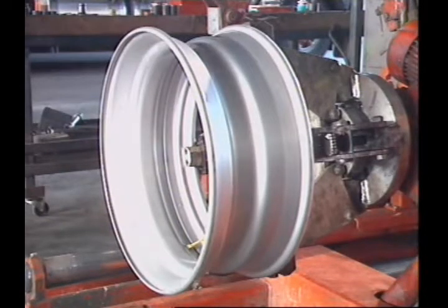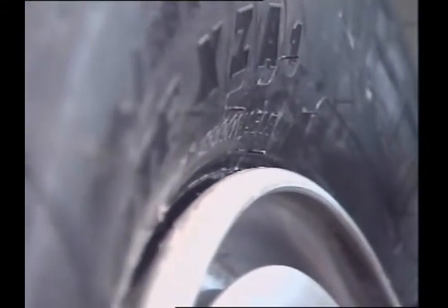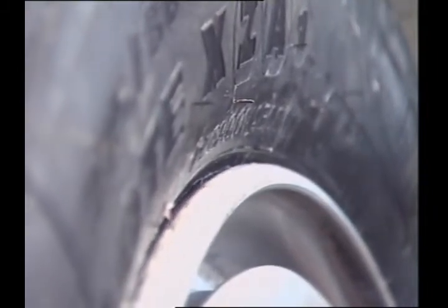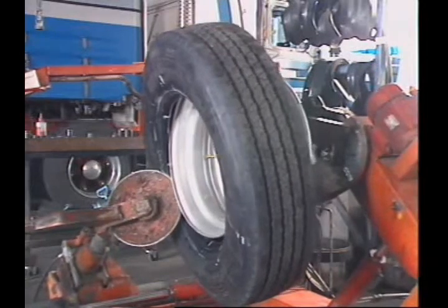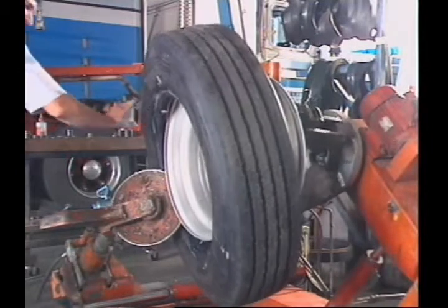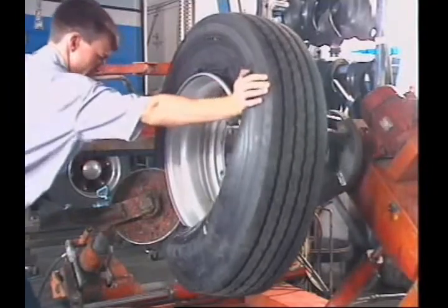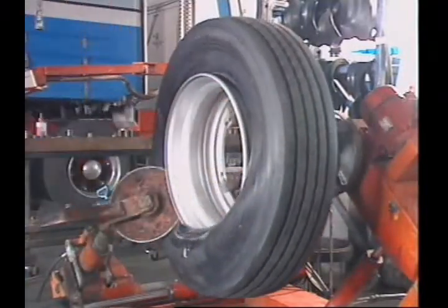Well-based rims can also be used on heavy commercial vehicles for tubeless tires. The rims are referred to as 15-degree drop center rims because the bead seats are inclined at 15 degrees towards the flange. The taper gives a good grip and an airtight seal between the tire beads and the rim. The low flanges and drop center allow the special size, flexible tubeless truck tires to be mounted and demounted in a similar manner to that used on smaller passenger car tires.